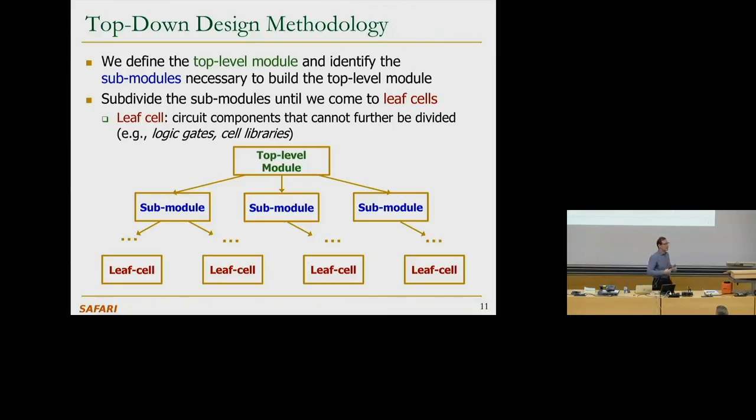And you don't want to divide the register, you just pick the register that satisfies your design points like performance, energy. You will see that this could be AND gates also, right? So this really depends on your library in the end. And the higher the level of abstraction and the ability for the designer to choose, the better, because they can be more productive, right? The lower the level of abstraction, if the leaf cell is a transistor, which is not going to be in any of the languages, the leaf cell starts with the logic gates, then it's a bit harder, right?